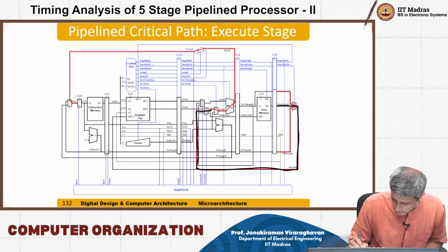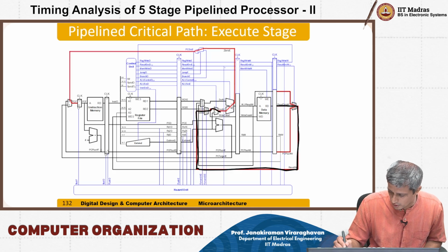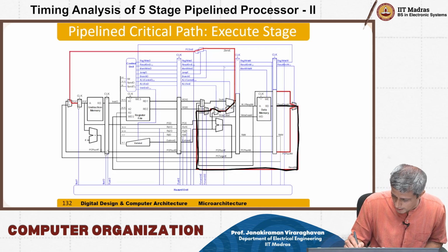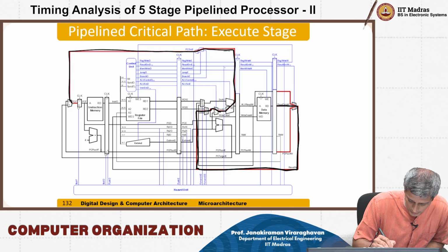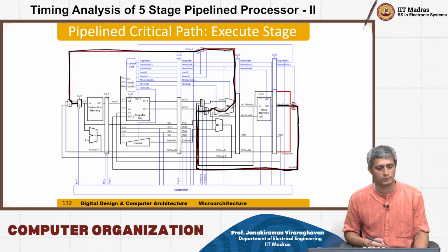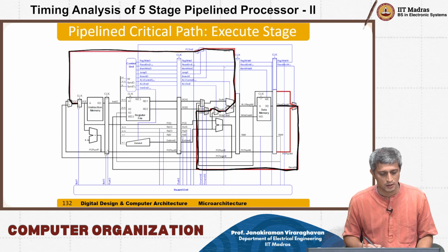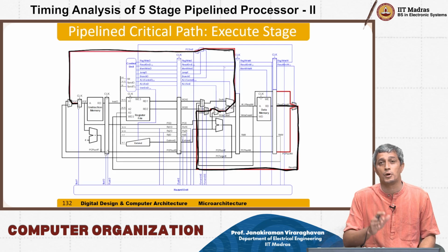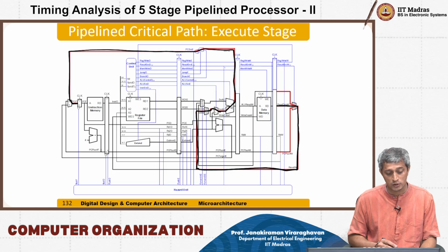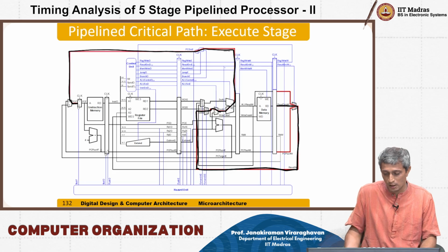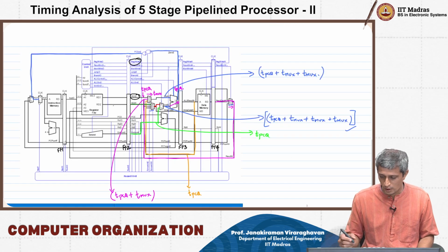in through one mux, two mux, and of course there is already a mux there, through the ALU, 0 flag, come back here, AND OR gate, come back through another mux to the program counter. That is the critical path of this particular execute stage, okay? So it can be tricky for us to figure out what the critical path is,